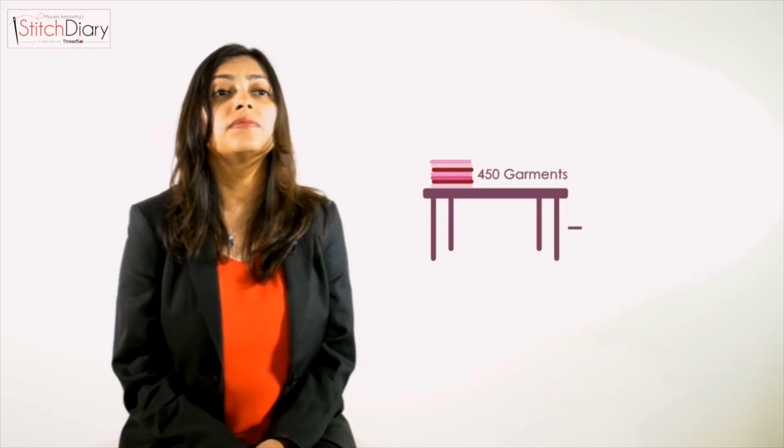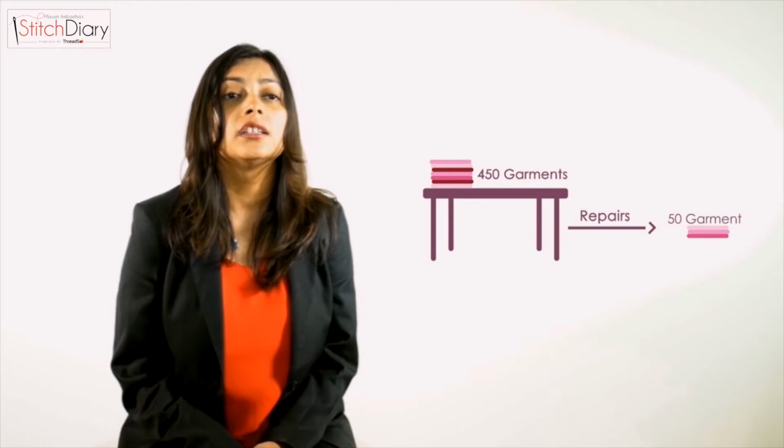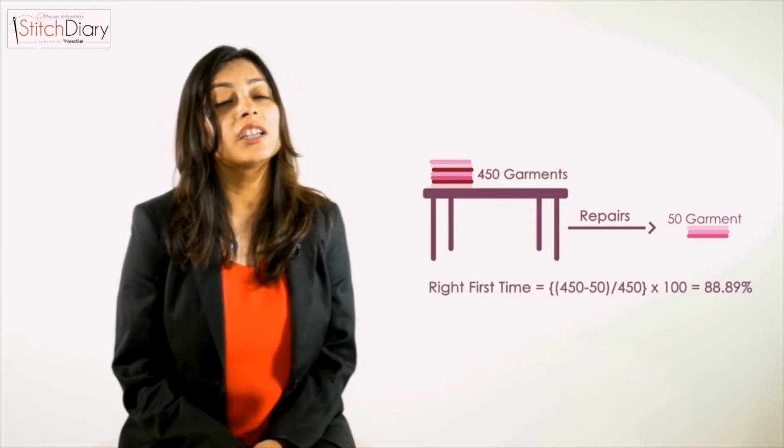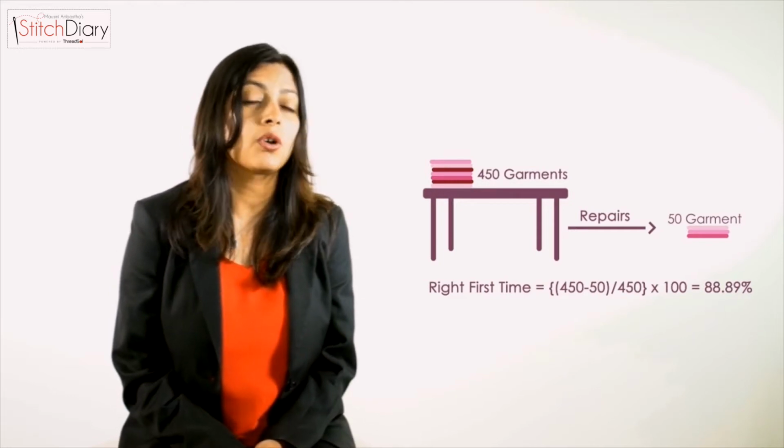To understand this with a simple example, let's say a factory or a line produced 450 garments and they are being inspected at the end of the line, out of which 50 garments were sent back for repairs or rework. Then the RFT level is 88.89% for that particular inspection point or that line.